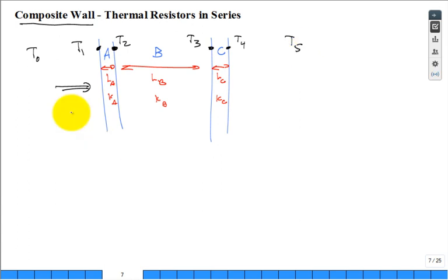And you could have the flow of heat through a network. And it's the easiest network. It's a series network of resistors. So maybe you would start, you put a node for where you have your temperatures. And in between the temperature nodes, you have little thermal resistors.